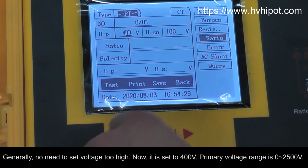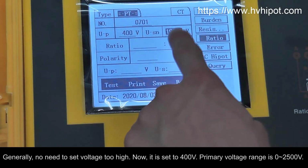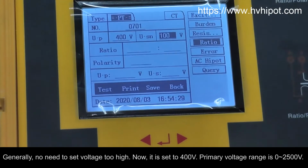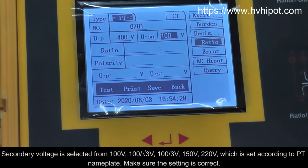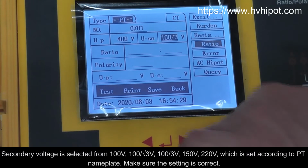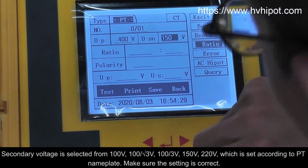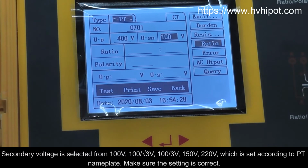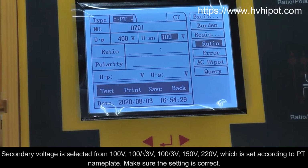Generally, no need to set voltage too high. Now it is set to 400 volts. Primary voltage range is 0 to 2500 volts. Secondary voltage is selected from 100 volts, 100 divided by square root 3 volts, 100 thirds of a volt, 150 volts, 220 volts, which is set according to PT nameplate. Make sure the setting is correct.